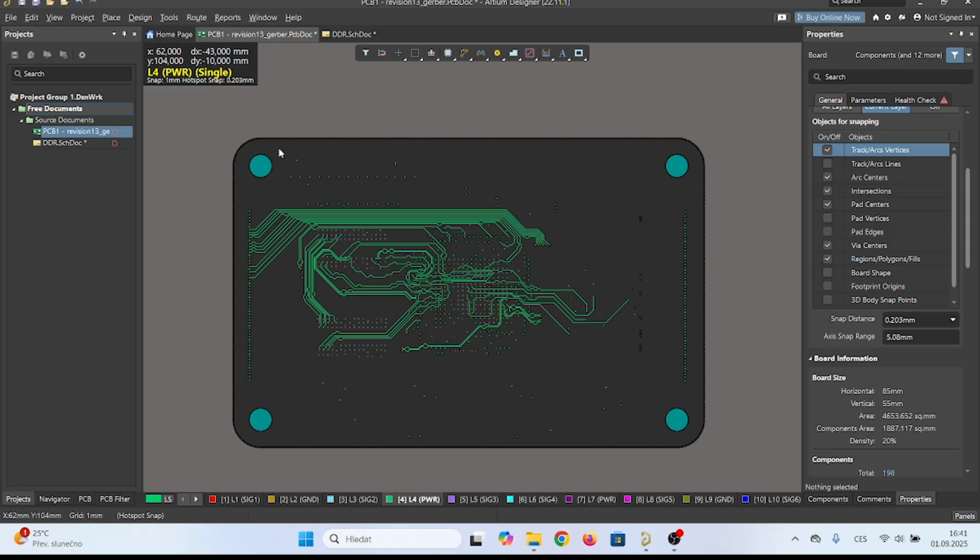And then you simply put your Gerber files, which tell the dimensions and copper traces and pours and polygons. So this is really a PCB description, and you send it to the manufacturer and it will create a PCB for you. And then you combine it with your bill of materials and pick and place files, and it will create a PCB and assembled board for you.